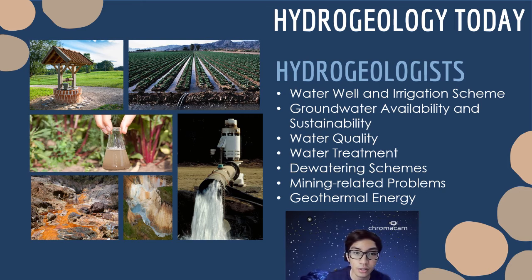They also investigate the quality of water to ensure that it is fit for its intended use. When the groundwater is polluted, they design schemes to try and clean up this pollution. They design construction dewatering schemes and deal with groundwater problems associated with mining. And lastly, they help to harness geothermal energy through groundwater-based heat pumps.